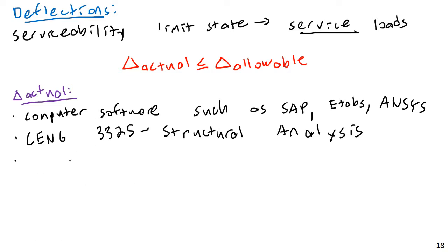For relatively simple beams, I don't just mean simply supported, but one or two spans, things like that, the steel manual also has some very good tools that you can use. You can find this on page 3-208, if I have my reference correct, in the 15th edition of the manual.